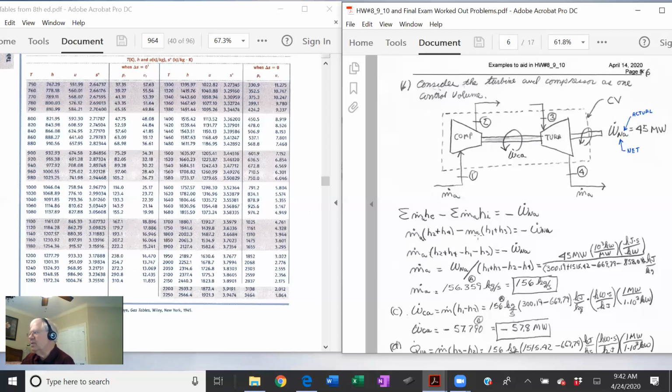Now we'll look at the enthalpies entering. H1 plus H3. There you go. Now you can factor out the mass of the air, m dot air, and you have H2 plus H4 minus H1 minus H3. You know everything in that equation but the mass of the air.